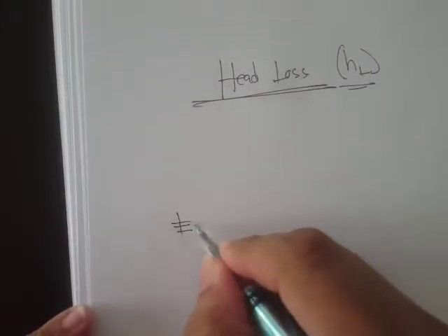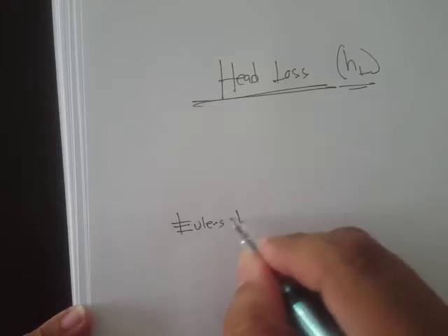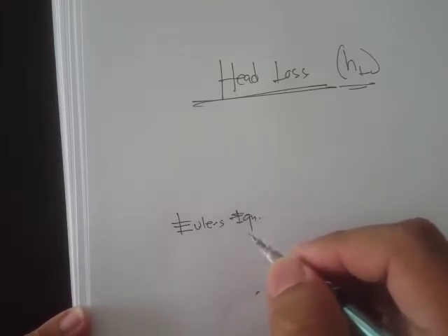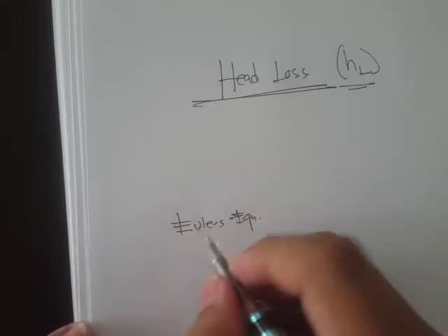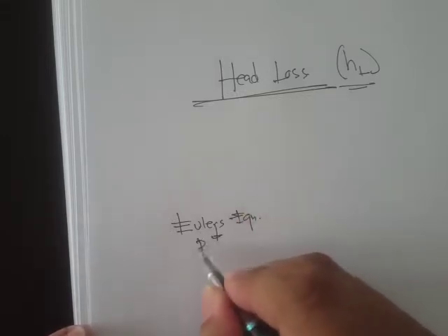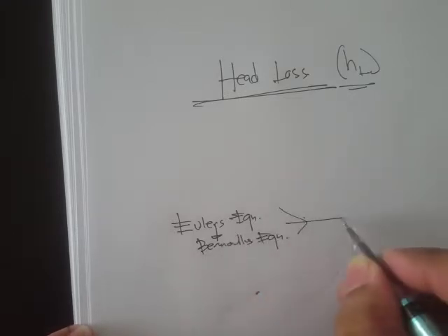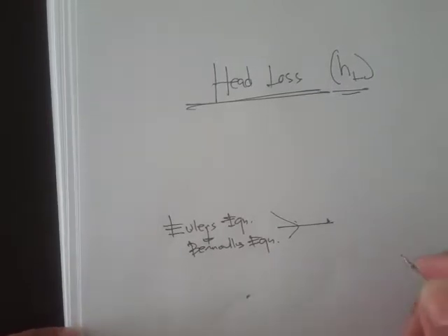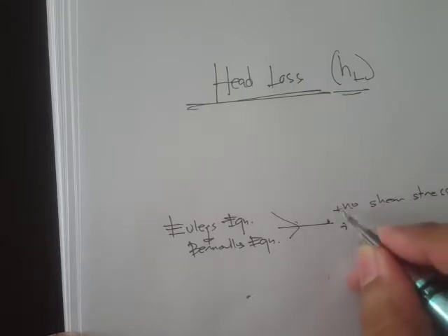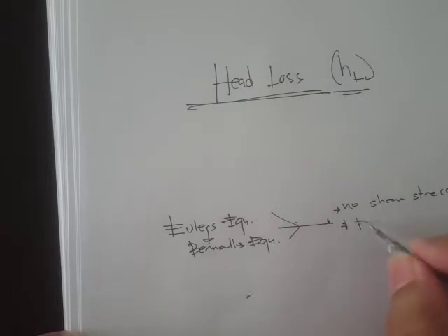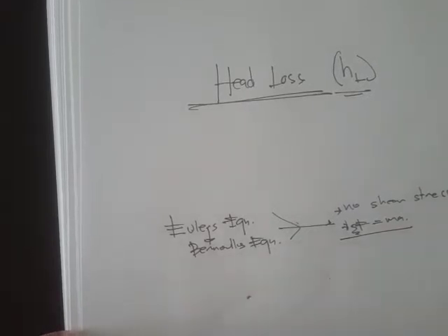To give you an overview, recall that we had Euler's equation before, Euler's differential equation of motion for fluid flow. Then when we integrate this, we have Bernoulli's equation. Except that in these equations, they don't consider the viscous effects, right? So no shear stress, even though we use Newton's second law, F is equal to ma. So in these equations, there's no shear stress.